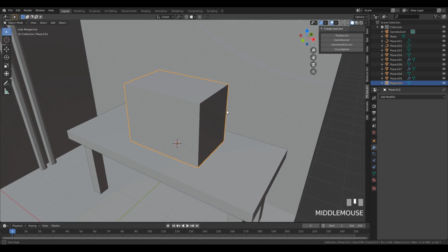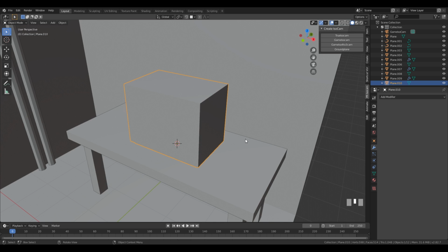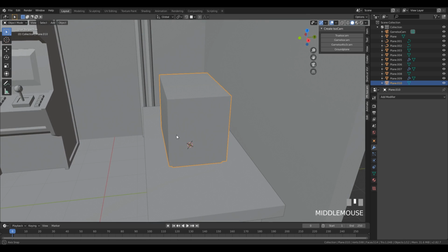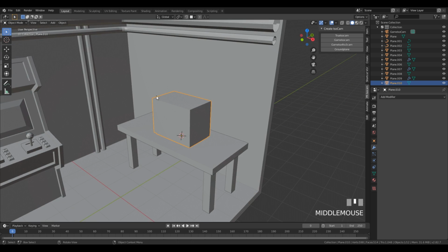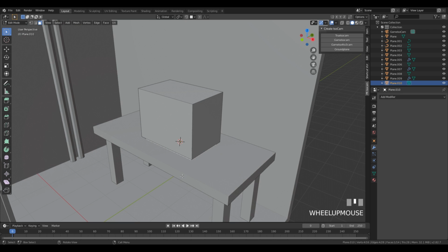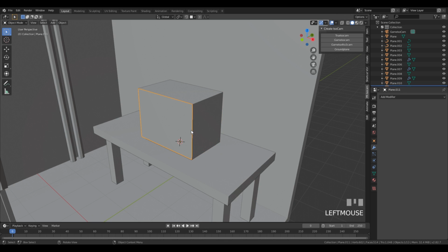and right now I want to create a screen here and some buttons and stuff, but I don't want to subdivide the whole cube. And since we are staying in the flat shaded low poly mode here, we can just separate the face as we please. So let's select the face here, let's press P, then separate, so we can see it's now a separate object.